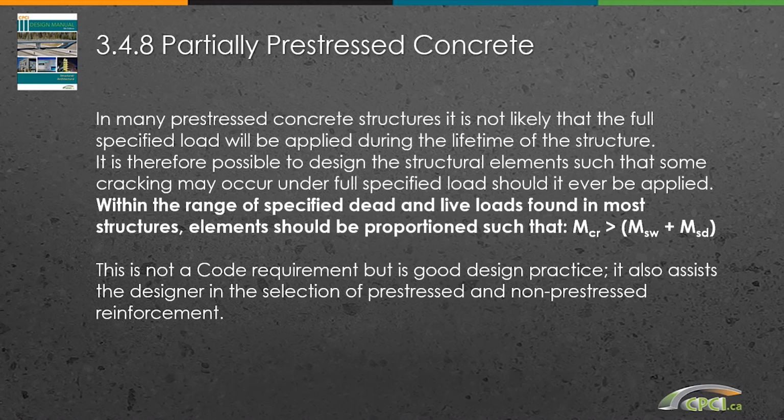And by doing that, we allow cracks in the pre-stress section, allowing stresses beyond the allowed in the code, and therefore allowing some cracks. And these cracks essentially have to be controlled again. Same thing that when we talked about 5-10 minutes ago, when we said about controlling cracks with the size of crack and the type of exposure.